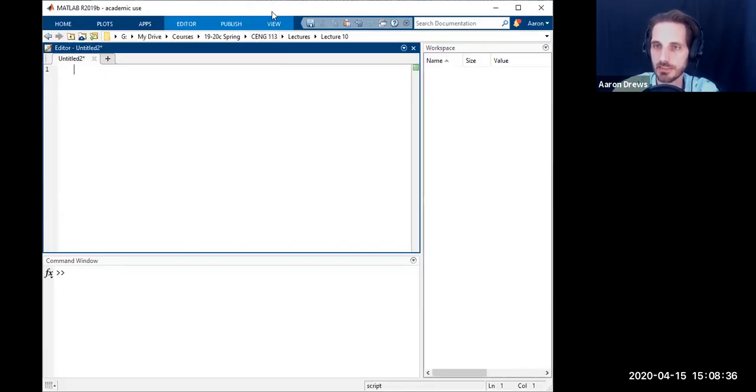So let's switch over to MATLAB here. The first thing I can do when I set this up is say, well, what do I want to solve for? I need to solve for my outlet molar flow rates. I'm going to opt to solve for both of them rather than just n sub A for a reason that I will show you momentarily in the script. So if I wanted to solve for both of them, that's two unknowns, right? It's n sub A and n sub B. You can set the whole thing up with just n sub A if you want to, and I will show you how you can do that when we get there.